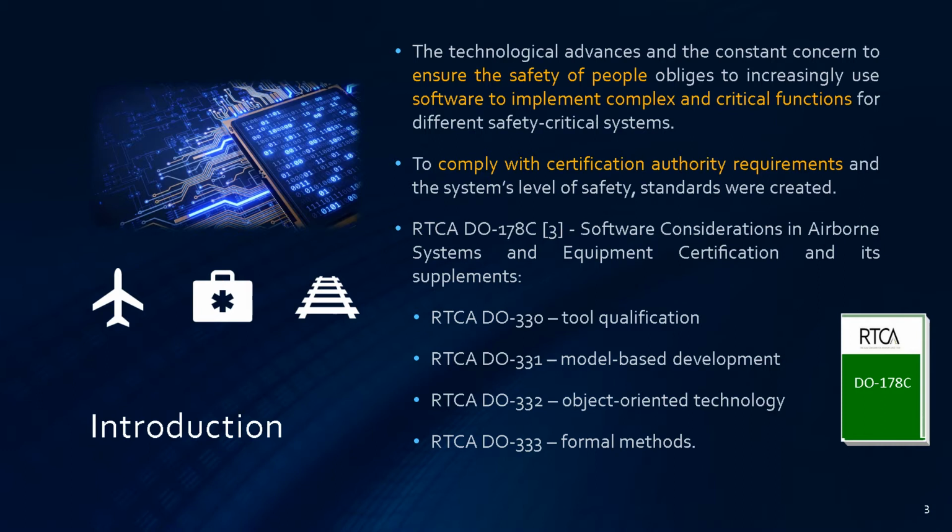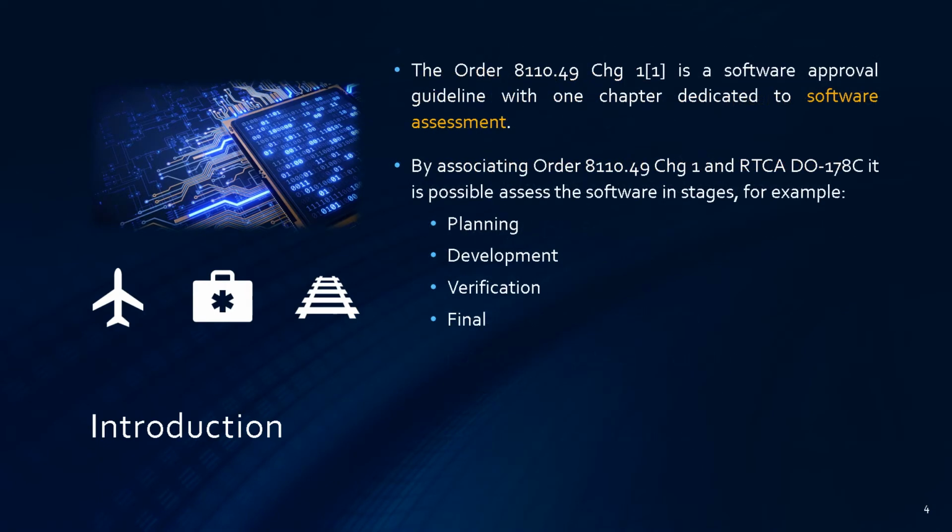One example of a standard for this area is the RTCA DO178C and its related supplements used as a means of approval. The certification authorities also created the Order 8110.49 Change 1, which has a chapter to discuss the software assessment and what is expected when conducting the audit.